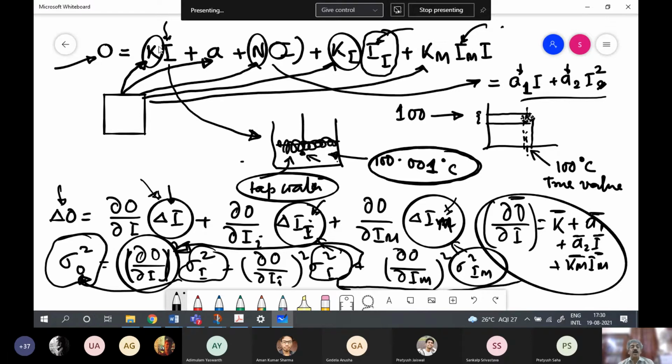So if you are trying to infer, you don't know what value you will get. If you buy a temperature sensor from that batch or from that specification, and you put it there, then what kind of variation will you get? Then you will have to additionally consider variations in these model elements also. Because what you know now is only some average values of a number of sensors coming from the batch. You are not talking about a particular sensor.